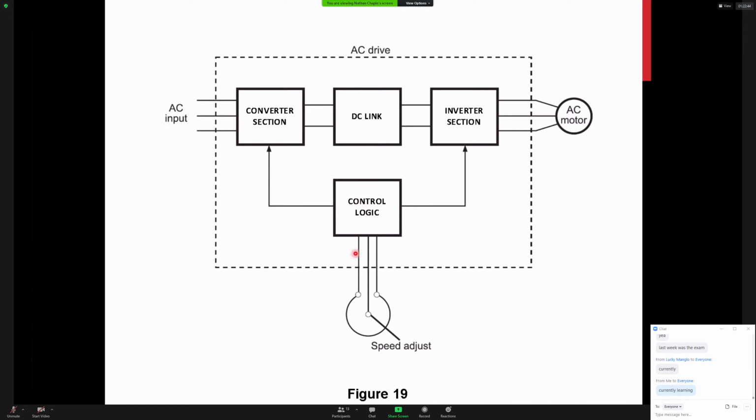And then attached to our CPU, there is a bunch of inputs and outputs. So just like with your PLCs, a variable frequency drive has digital inputs or discrete inputs, digital outputs, and then it also has analog inputs and analog outputs. So the same sort of complexity is involved. The difference being with a variable frequency drive, you are setting parameters.